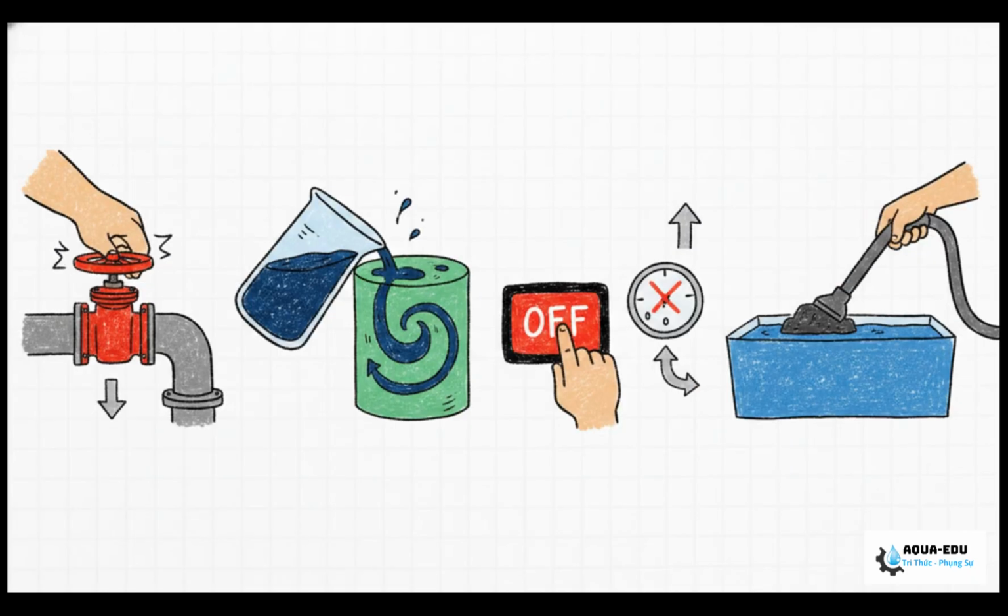In those first 24 hours, your goal is pure survival. You have to immediately cut your influent flow down to 50 to 70%. If you don't, you'll completely overwhelm the biotanks. Next, temporarily bump your chemical coagulants up by about 20 to 30%. Since you don't have any bubbles to float the sludge, you've got to try and force some gravity settling right there in the DAF tank.